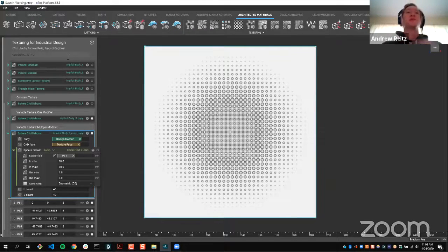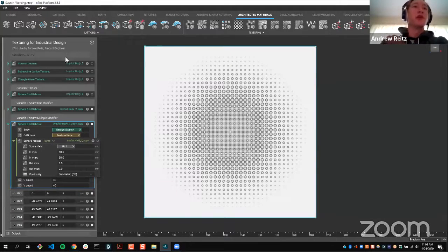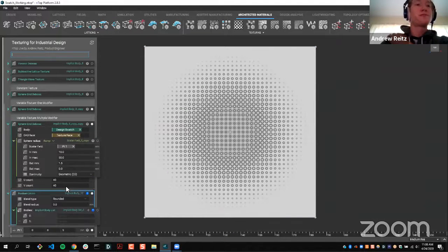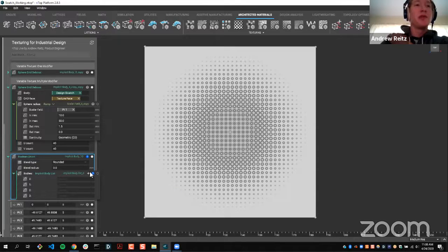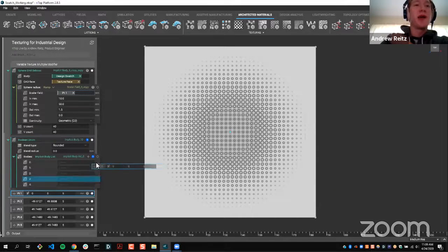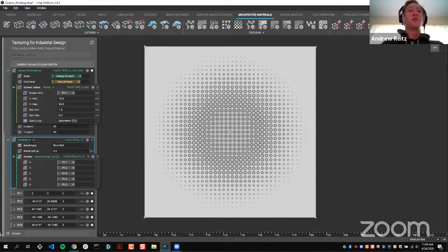There's a couple ways to do this, but in this example, I'm going to show you how to do a Boolean Union. So if we add a Boolean Union block, I can expand the number of inputs, and I can simply add all 5 points together. So I've joined all my points. I'll turn this into a variable. I'll call this my joined points.